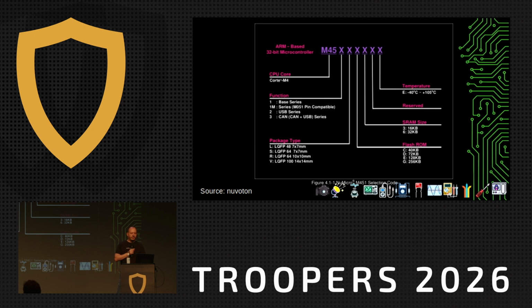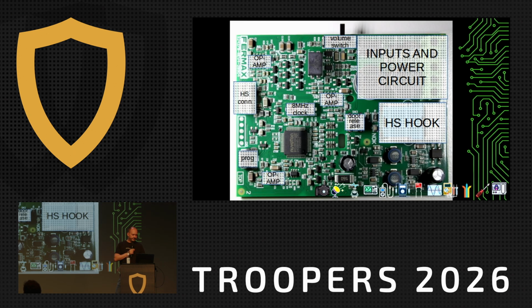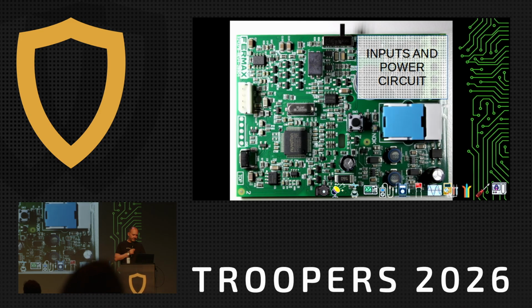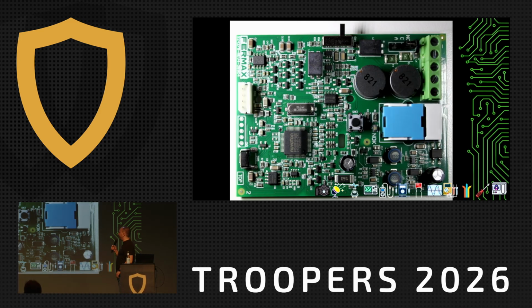So then your question basically becomes: is it possible that somewhere here there is a component that does encryption on the signal? Well, I don't see any, because the three 4x2s are op-amps, and all the other components on the board are three pins maximum. Well, we have some filters there as well. So there just aren't any components on the board that can do that. And do recall that I did the dump of the signal, and you can visually see the audio being sent.